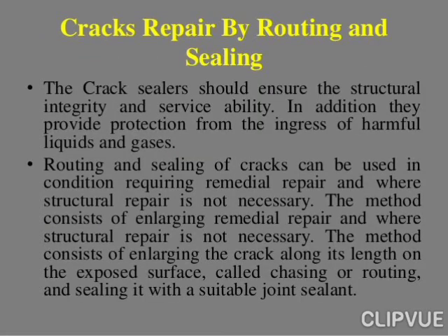Crack repair by routing and sealing. The crack sealers should ensure the structural integrity and serviceability. In addition, they provide protection from the ingress of harmful liquids and gases. Routing and sealing of cracks can be used in conditions requiring remedial repair and where structural repair is not necessary.